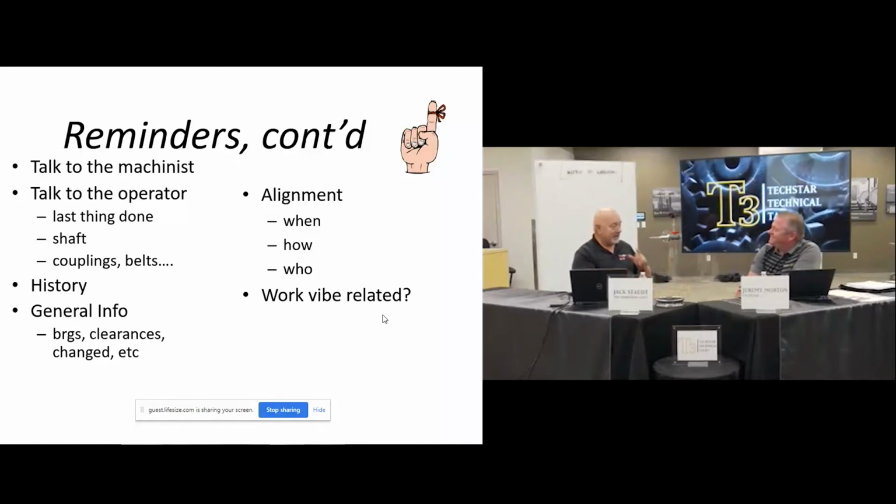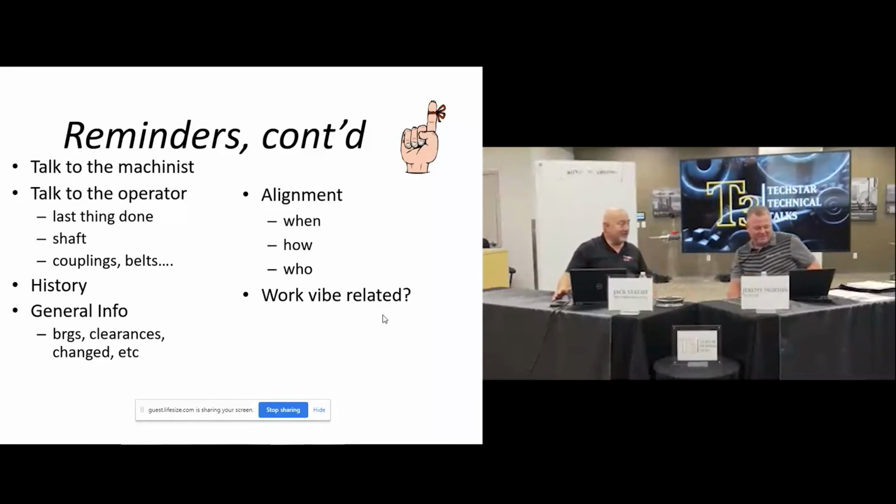So new policy, and this was in the early 90s when this was going on. New policy now, we don't align at the feet, we align at the coupling. That was a big change. Once we came back and put the new element on there and put the Optalign lasers on, the beam went completely off. It was so far misaligned, and they just couldn't believe it. They go, we never moved the feet. Yeah, how did it get that way? So that could have been a catastrophic failure. That was a good catch. Yeah.